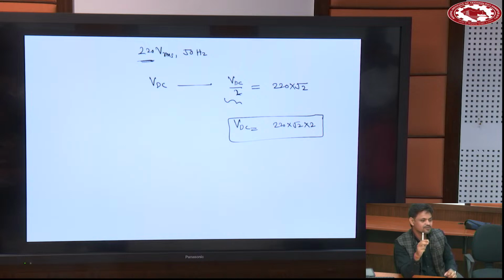Actually, in the inverter you have seen in simulation, this much is the DC link voltage, this much is the AC. Then how is the DC link voltage calculated? Using this formula only. This is for modulation index 1, where you have used the full range; the sine wave is touching 1, duty ratio is touching 1. If you are limiting it to 0.8, modulation ratio is 0.8 only, you require more DC to produce the same voltage. Okay.